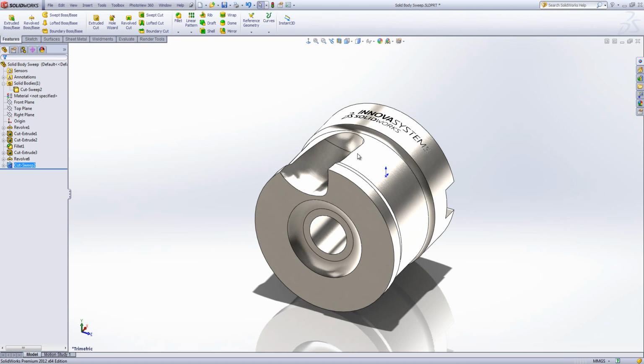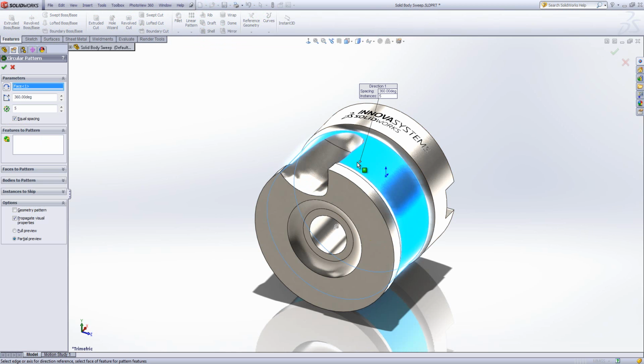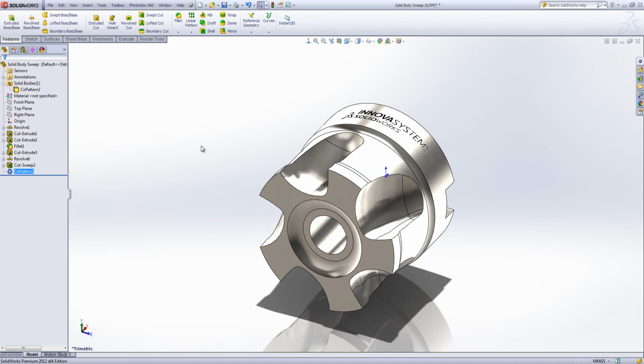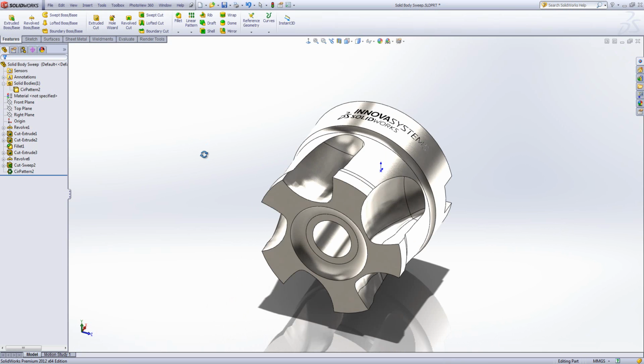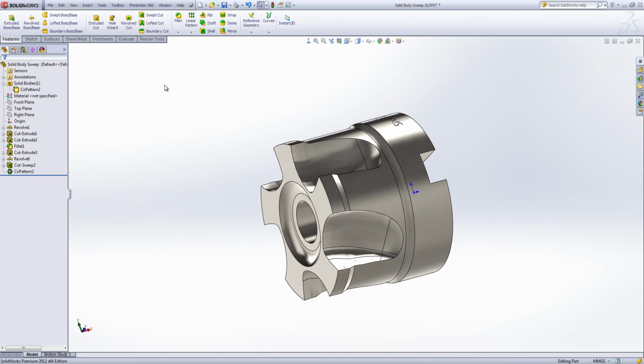So to finish off this design, I'm going to go ahead and create a straightforward circular pattern. Within this design, it often takes a long time to rebuild when we're creating it for a circular pattern as well. One thing we can do is just turn on geometry pattern. It will just take exact copies of the geometry rather than the feature itself. And there we have our milling tool created. And you can see the geometry that's been designed with this is different to what we would have got if we'd just used the profile on its own.